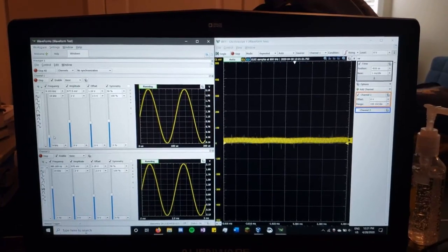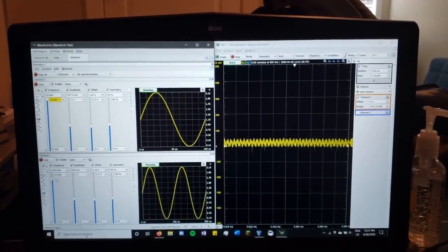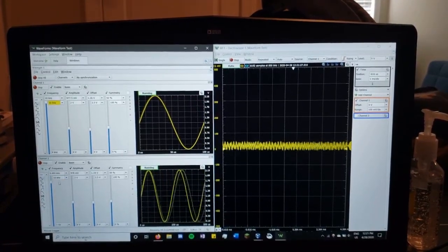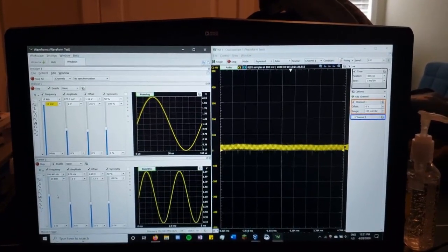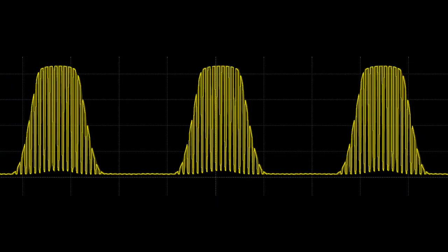When testing the circuit at different bias values, you can vary the amplitudes and frequencies of the inputs using the Analog Discovery tool and connections to the GPIO pins on the FPAA. At an NFET bias voltage of 2.5 volts and an OTA bias current of 5 times 10 to the negative 7 amps, we were able to produce amplitude modulation when multiplying two sinusoids, which is a good indication that the circuit is behaving correctly.